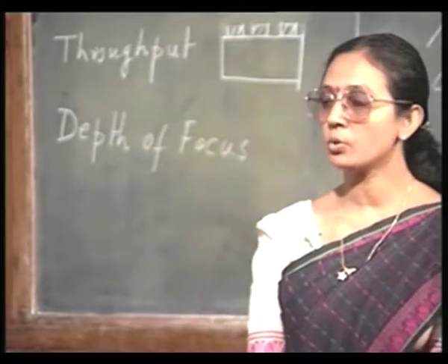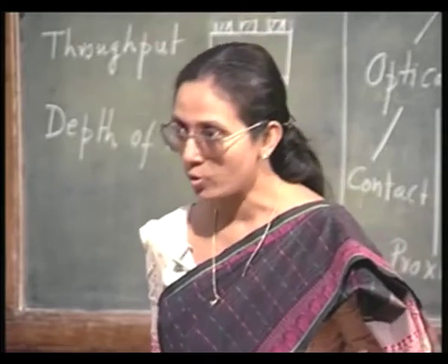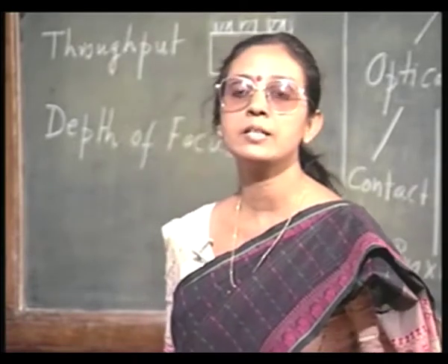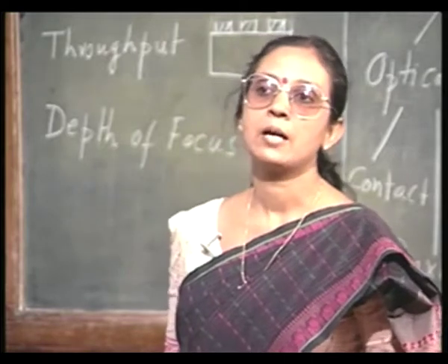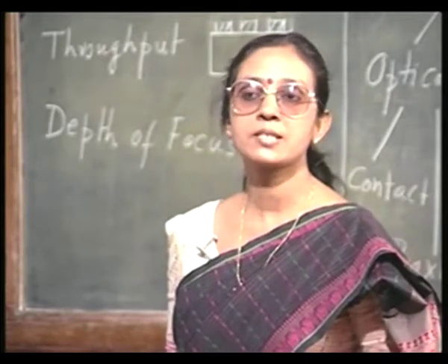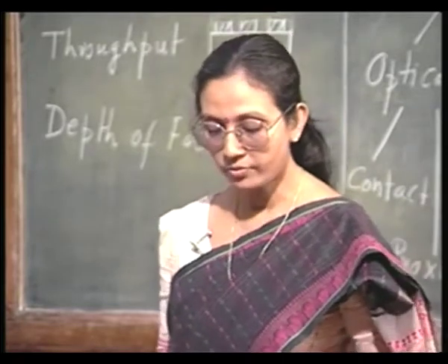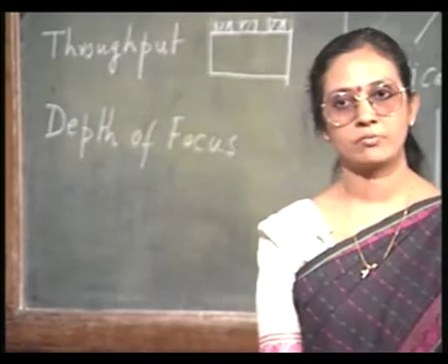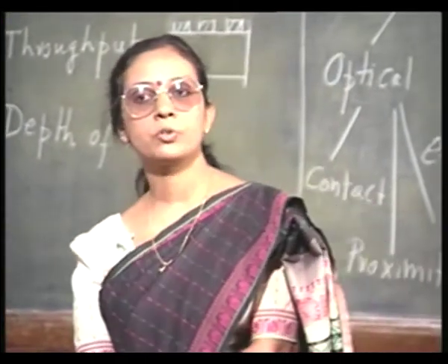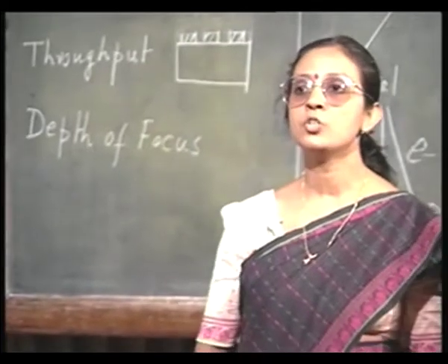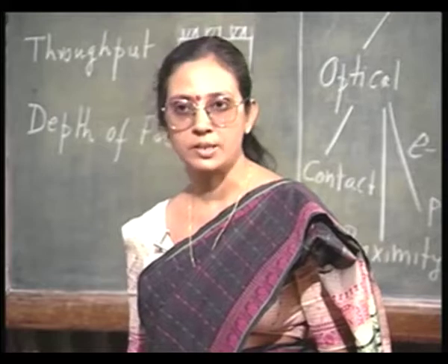Now, let us come to the question of photoresists. I have already told you that if it gets softened on exposure, it is a positive resist. If it gets hardened on exposure, it is a negative resist. Why or how do these resists get softened or hardened? I will take the case of a negative photoresist first. You see, a negative photoresist actually has 2 constituents.